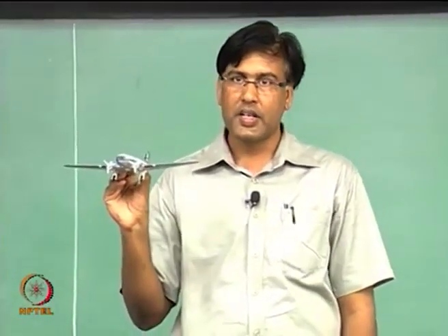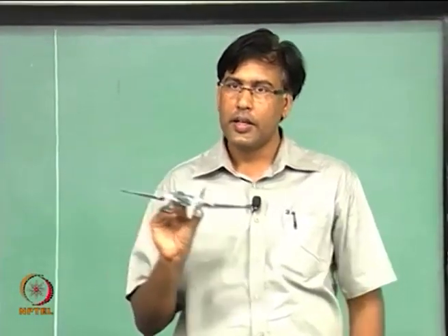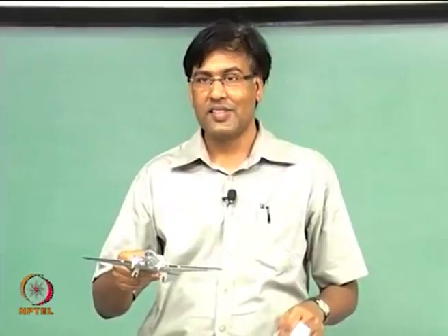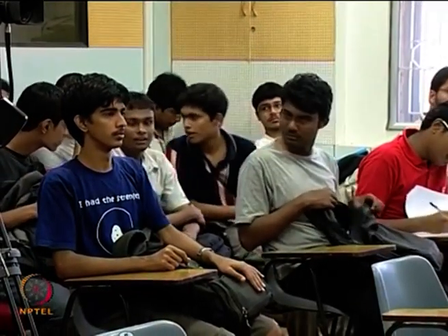So, that is why we are talking about this CL beta less than 0 for roll stability. When you bank, doesn't it go into sort of a turn motion? No, that is a wanted turn. You are executing it. This is not really a turn. What I am saying, there is a roll upset from the level flying condition.